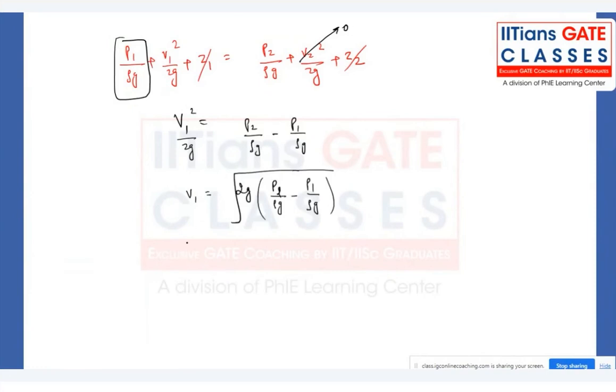And here, whatever we are measuring, the velocity of the fluid, we are simply writing in terms of this; the g will cancel out. So V1 equals under root of 2 by rho times stagnation pressure minus static pressure.